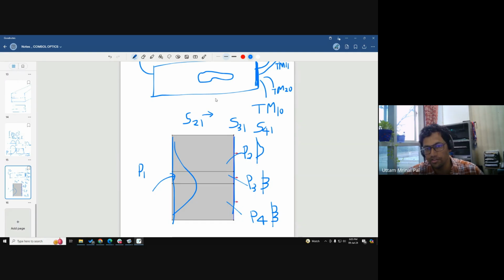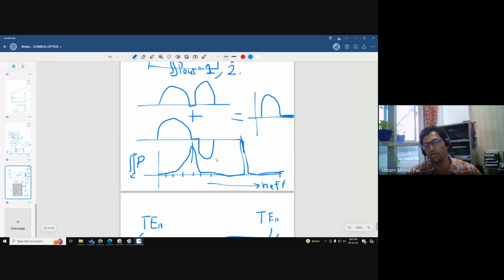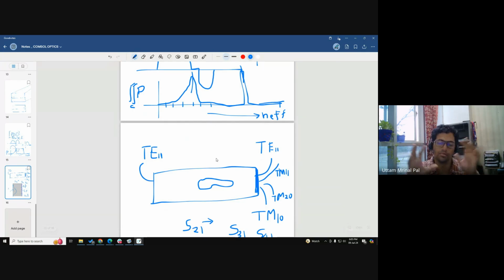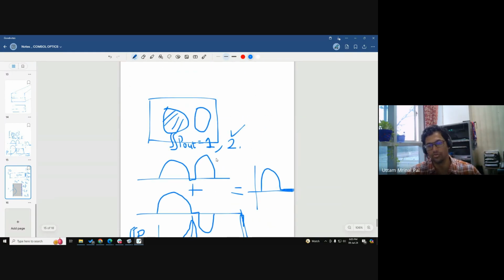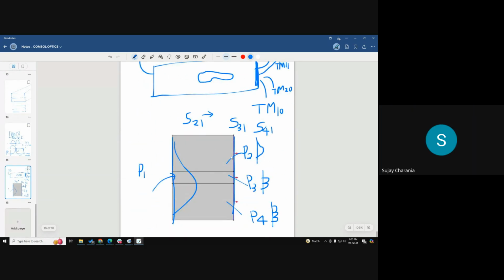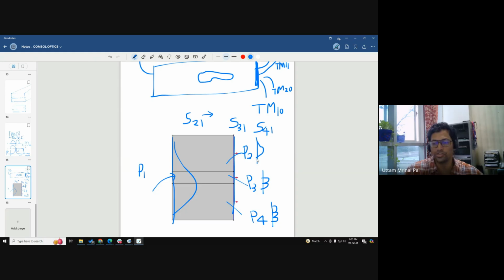But surface integration, if you do that, you cannot do this. You have to play around with the port. Surface integration will always have all the electric field involved, so it gives the whole surface power. So you use this port setting, because the port setting has the ability to differentiate the power flow for particular modes. This is the mathematics, and principally this is how people do it, but you need to sit and check how true it is. But principally this should work.